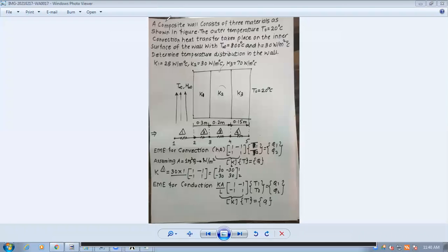You need to measure the location of every node. But if you need to measure the location of every node, with respect to what node you are measuring it, that you need to define first. So that means you need to assign one of the nodes as a reference node, right? Getting my point?